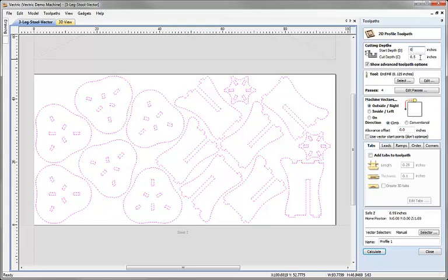Now there's a variable we can use in a calculation within the form here to get the depth of our material if we can't remember the value. And so in here I could type Z and hit the equals sign on the keyboard, and that will automatically fill in the value that's equivalent to the Z depth of our material.